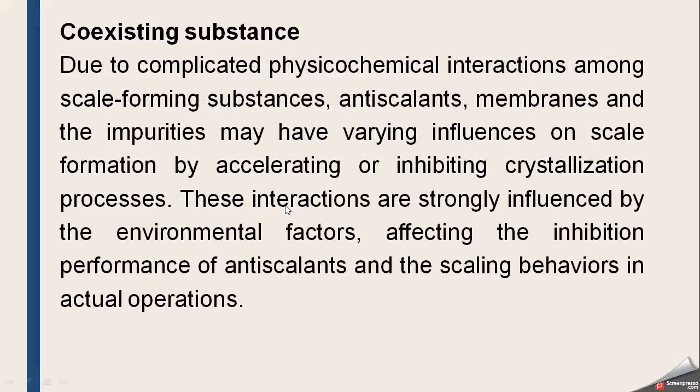Now, there are different complicated physiochemical interactions between scale forming substances, antiscalants, membrane and impurities, and these complicated physiochemical interactions influence the scale formation by accelerating or inhibiting the crystallization process. It can go on both sides, that these interactions may lead to crystallization or maybe inhibit the crystallization processes.